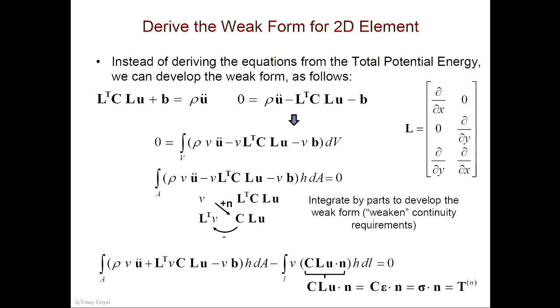Now in the previous lecture for heat transfer, I divided that surface integral into two. I didn't do it here. One where essential boundary conditions are specified, one where natural boundary conditions are specified. We already showed in the previous lecture that the ones where essential boundary conditions are specified will vanish, because V will be selected as the basis functions, and the basis functions vanish at the location where essential boundary conditions are specified. Okay? That's why I didn't go through that exercise, because we covered that in heat transfer. I don't want to repeat that here, but I repeated it verbally, and hopefully you can remember that.